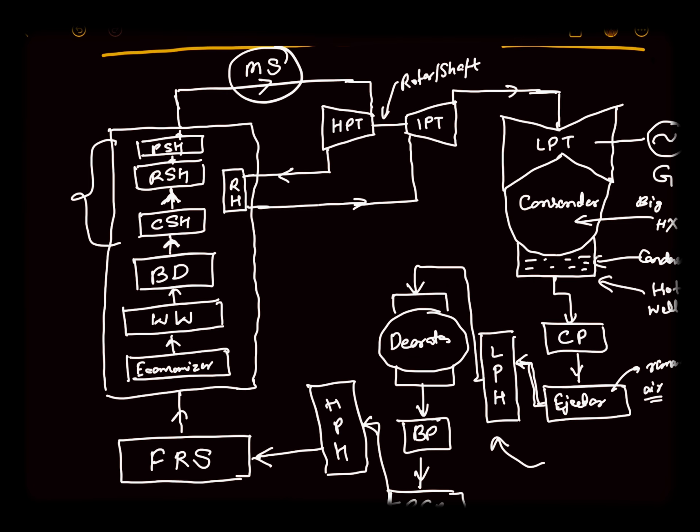And the pendant superheater is actually used to reduce the temperature. If anyhow the temperature from the convective superheater and radiative superheater becomes very high, then the pendant superheater is used to decrease its temperature. So it is mainly used for regulation of the temperature released from the boiler.